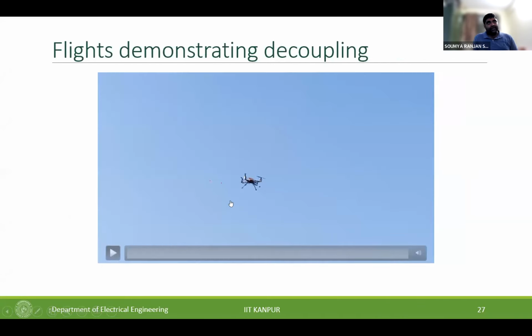So now those demonstrations were for cases when the diagonally opposite rotors had coupled tilting, so they tilt in the same direction. But these servos are capable of getting different tilt commands, so the control allocation now changes. The three force components and the three moment components can be allotted to 4 rotor speeds and 4 tilt angles, and this actually gave us freedom of even doing better.